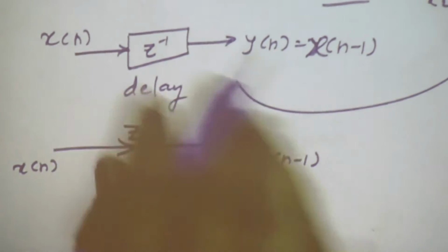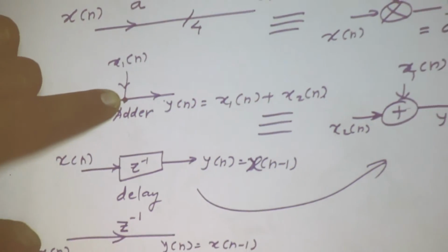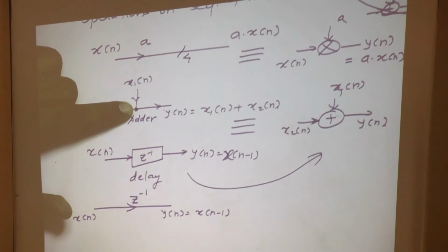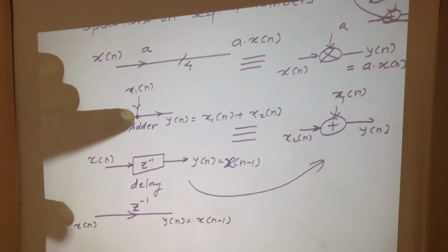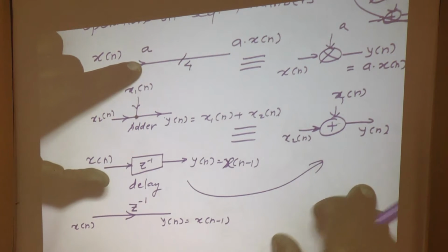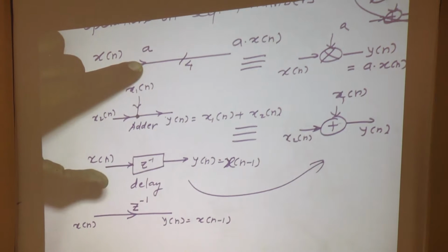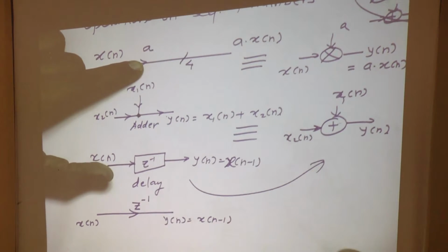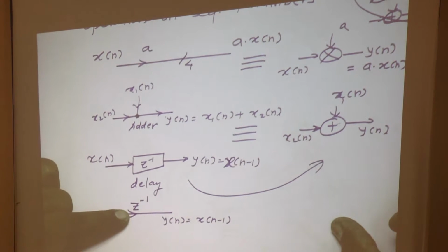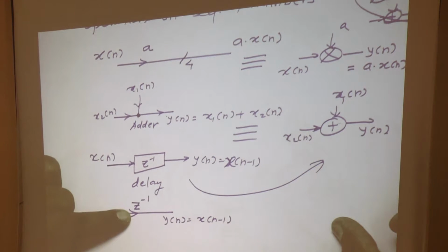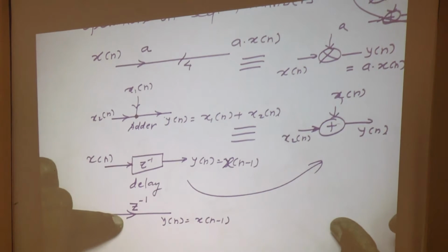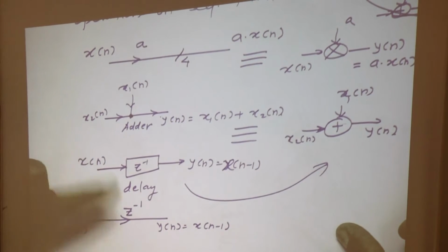What is this? You understand adder. Just now I explained an adder, full adder, 8-bit full adder, n-bit full adder, 16-bit full adder, 32-bit full adder. It could be adding two floating point numbers, it could be adding two double precision numbers and so on. A multiplier similarly is an n-bit multiplier. These are all combinational logic blocks with reference to digital circuits, whereas the only sequential block present in the architecture of discrete time systems is Z inverse, which is delay, and this delay is nothing but any of the flip flops, delay flip flop, JK flip flop, SR flip flop, or any other flip flop.